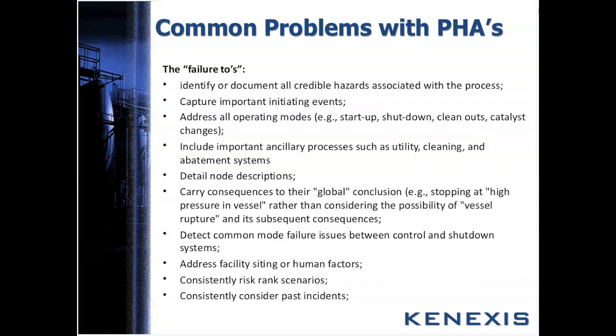Document all the credible hazards. Cover all initiating events. Cover all the different operating modes, which is required by PSM for regulated processes. They don't talk about, a lot of times, ancillary processes, utility cleaning, abatement systems. They don't detail the nodes very well, so it's hard to tell what's covered. They don't carry the consequences to a global conclusion. If I've got on this node I'm talking about a pressure event, it may have upstream or downstream effects. Those need to be denoted.